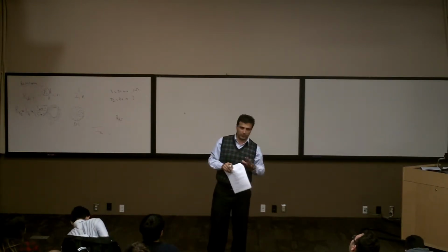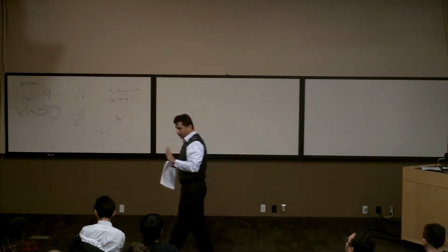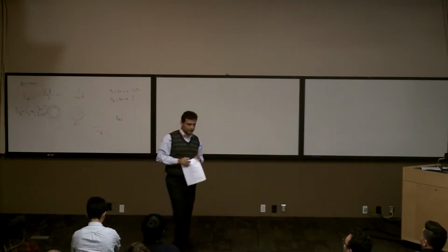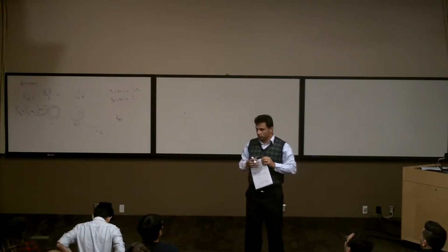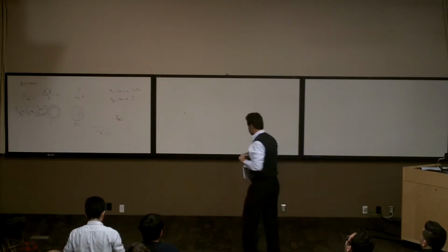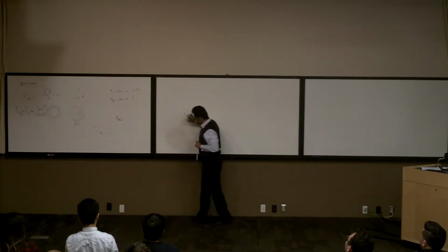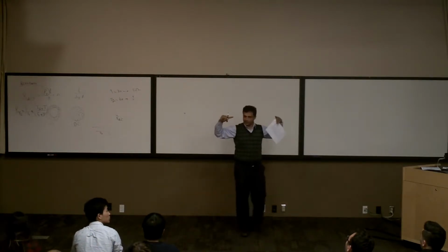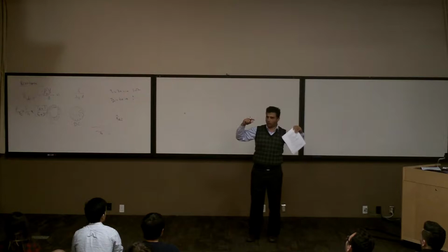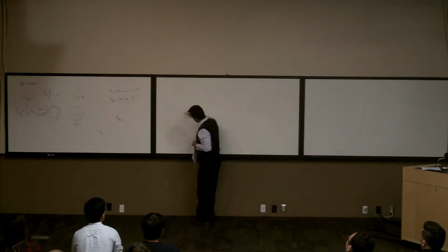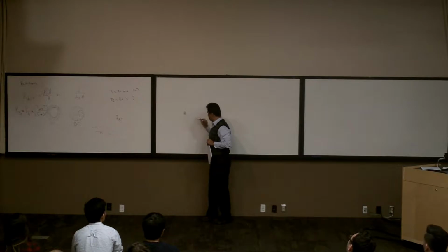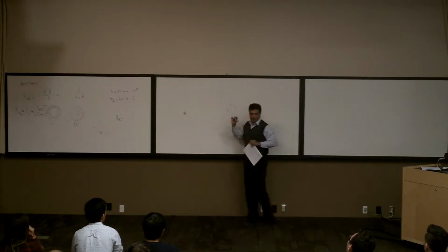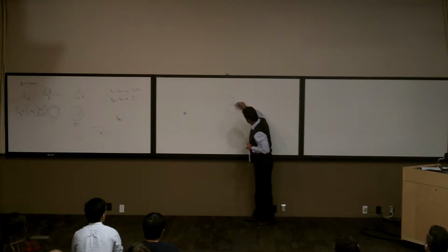But what's the problem with aluminum? The resistance is a little bit higher. But what's another problem with aluminum? It doesn't have the mechanical strength, right? It can break easily. So to fix that problem, they do this. They put a kind of steel here. One strand is steel, which is mechanically pretty strong, right? And now they put the rest of the conductor strands like this around it. So the middle one is steel, and these around it are aluminum.